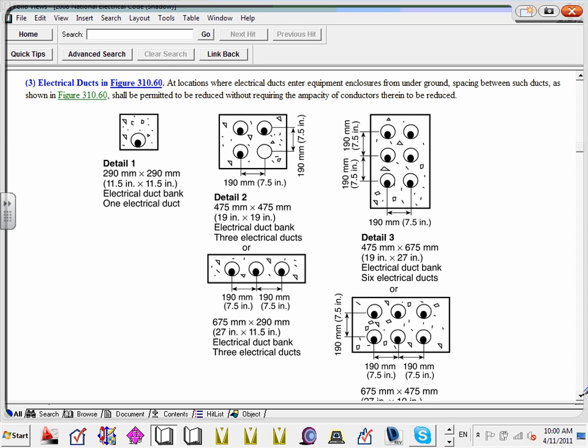The same thing, guys, here. It could be single conductor or multi-conductor cable. This one is the single most important one, guys. In this case, I can have a multi-conductor cable, 2 circuits, circuit 1, circuit 2, or as a matter of fact, I can have 6 circuits, 3 multi-conductor cables here, 3-phase cable, 6 conductors, 3-phase each in one combination. All of them are ducts. Spencer, look how far they move them away from each other, 7.5, 7.5, and in between them, what do you guys think? This is concrete encased. Concrete encased. That's how they do it most of the time when they go underground.